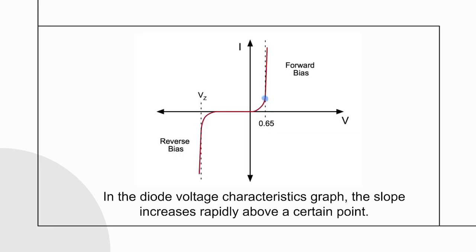Step 2. One of the features of the diode graph, rapidly increasing from a certain voltage or more, should be implemented. Among the exponential function graph properties we looked at earlier, we multiply the x value of y equals e to the x minus 1, using the characteristic that the slope of the graph increases as the exponent increases. This exponent also sets the slope, but it also serves to set the value so that the current can flow rapidly at about 0.7 volts.